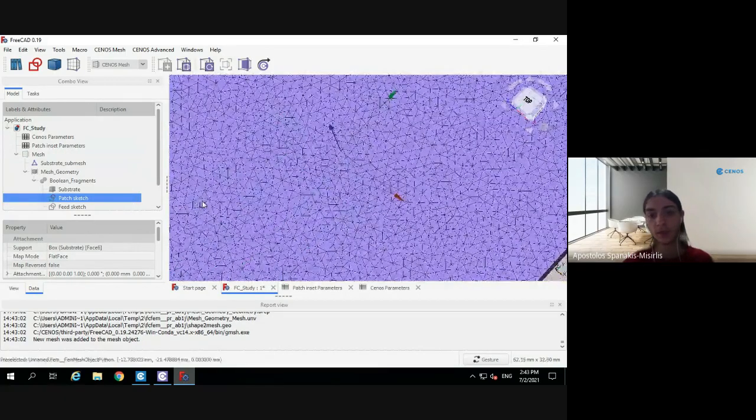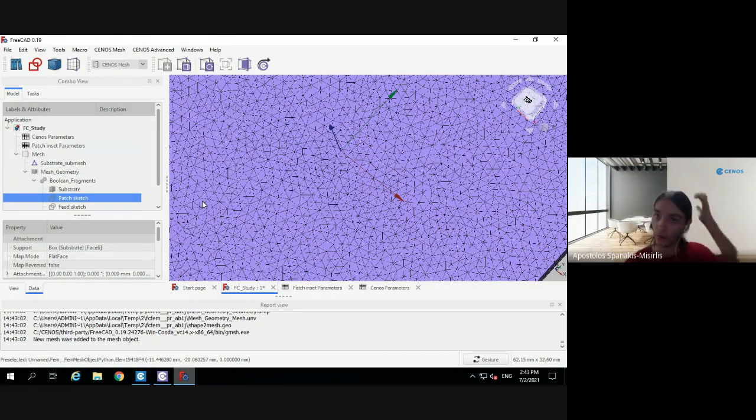Okay, so you might say that this is great. We've made it finer. We'll get more accurate results. And while this is true, we have increased the entire mesh for the antenna when we only need to increase the resolution near the edges of the inset feed line. And this poses a risk of significantly increasing the simulation runtime, which is obviously not something we favor. We want our simulations to run as fast as possible and give as accurate results as possible at the same time. So there's actually a workaround for this.